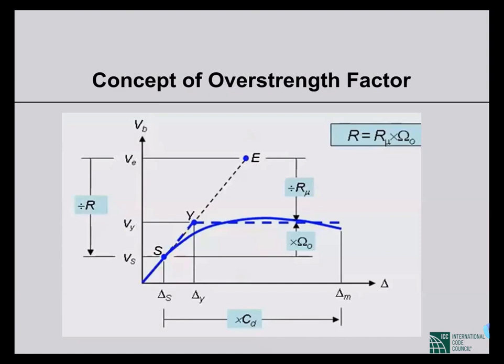But we know that we cannot design like that. We cannot design our structures as elastic. So we allow inelasticity. If our structure showed a bilinear behavior, that is elastic, perfectly plastic behavior, then we could get the blue dashed line.